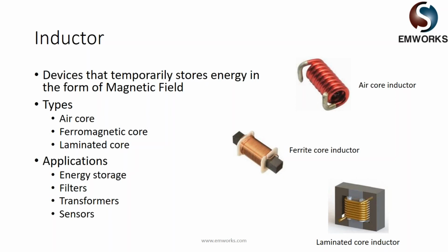Okay. Then the next classification, or the next level of inductor, with a higher level of sophistication, is the ferrite core inductors, where you have some sort of a core which acts as a conduit for your magnetic field. Obviously ferrites have a much better magnetic property than air, and hence this inductor has a capability to store a lot more magnetic energy or magnetic flux. So this ferrite core inductor, as you see here, is the next degree of sophistication.